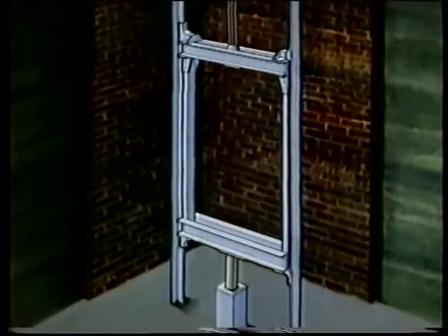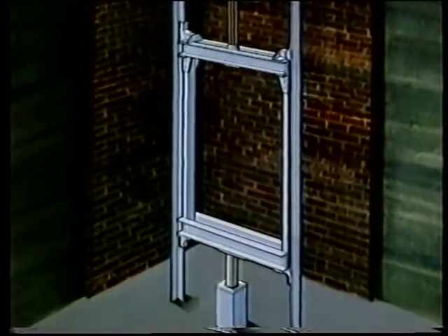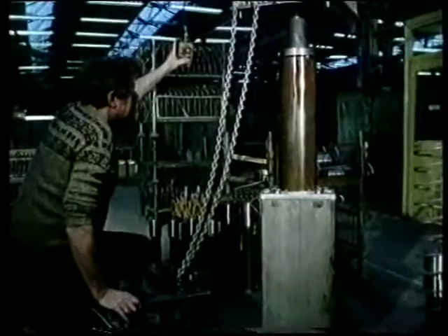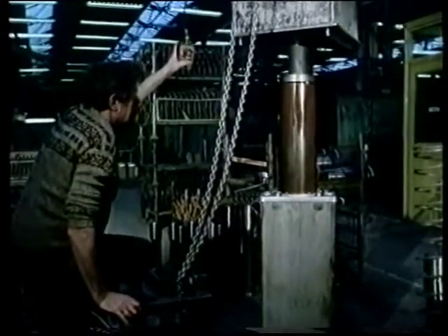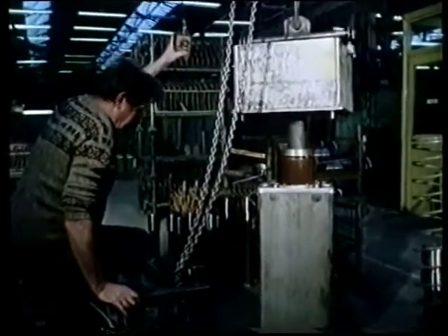The car itself runs on guide rails. The guide shoes on the car keep the path of the car in line. Should the car approach too close to the base of the shaft, a buffer will absorb the kinetic energy of the car, and under these circumstances, the base beam undergoes bending upwards. The buffer itself, one's under test at assembly here, absorbs the car's kinetic energy by means of a hydraulically damped piston in compression.